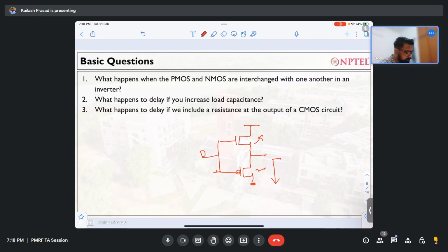So if the circuit's VDD is 5 volt, and the mod of VTH-N and VTH-P is 1 volt, what will happen whenever you provide 0 over here? If my input is in and this is output y, and the input is 0, what will the output be?